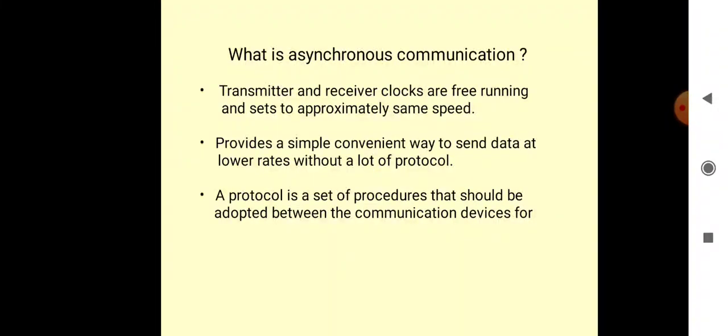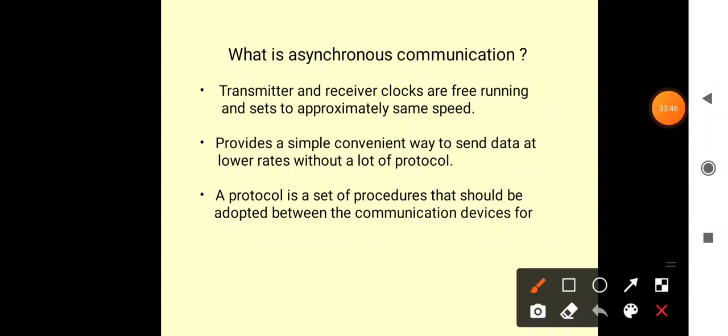Whereas in serial type of communication, one bit follows another. So we need only one communication channel. That is the reason whenever you want to transmit by serial transmission, parallel to serial conversion is done at the transmitter.